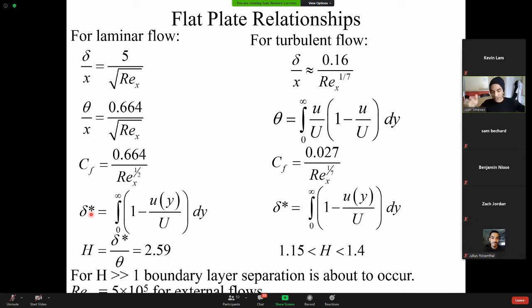Essentially we did the same thing, applying the conservation of momentum to the flat plate: momentum going in, momentum going out, and looking at whatever that deficit was, which is really the amount of force the flow is applying to the plate, was equal to that momentum thickness.